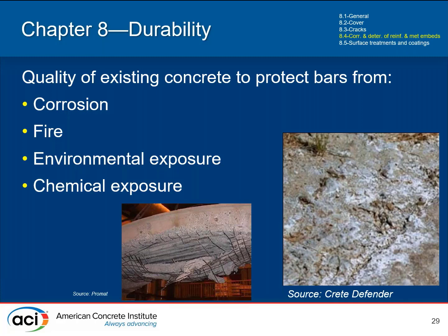Protect the bars from attack so that they're not corroded. Protecting bars from fire so that they're not exposed to the fire directly. It's got a little bit of insulation effectively so you can get your fire rating, your couple hours of fire rating. Protecting the bar from environmental exposure, preventing the bar from chemical exposure, because